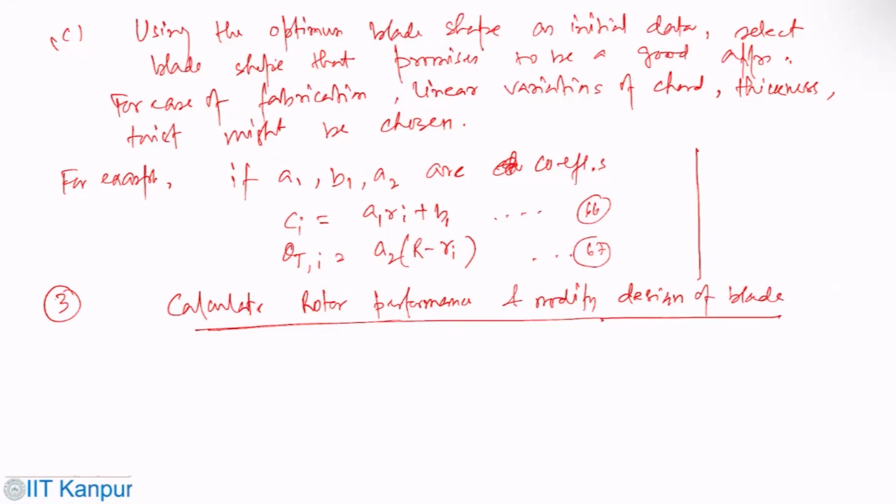So for method one, again, you solve for CL and alpha. We can find the actual angle of attack and lift coefficient for the center of each element by using the equations and the empirical curve.